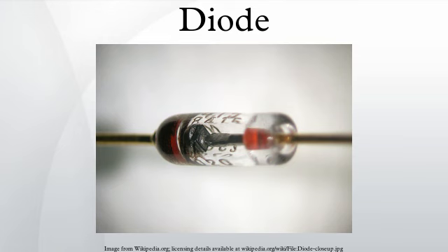Superbarrier diodes. Superbarrier diodes are rectifier diodes that incorporate the low forward voltage drop of the Schottky diode with the surge handling capability and low reverse leakage current of a normal PN junction diode.